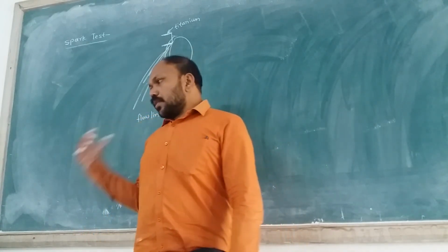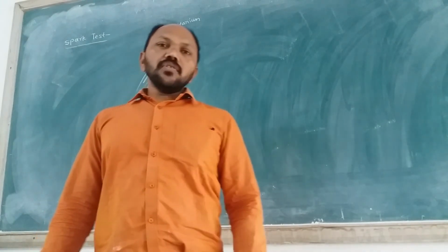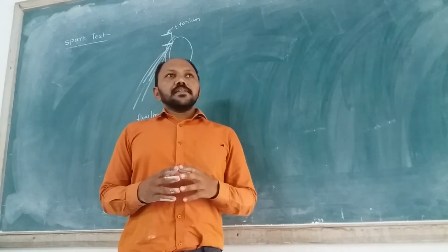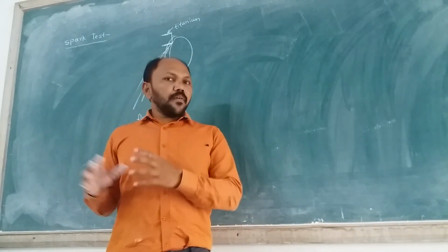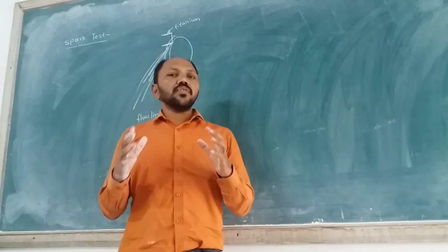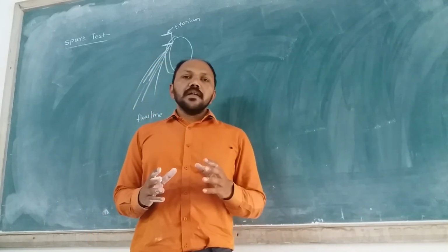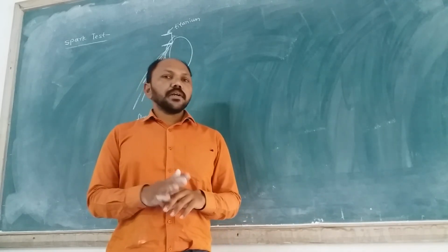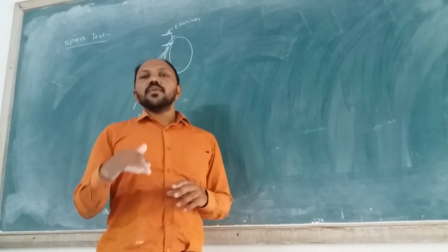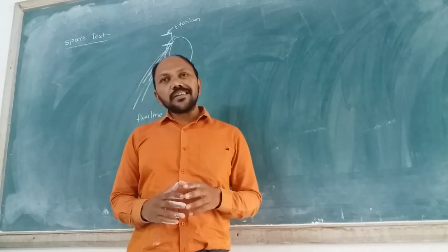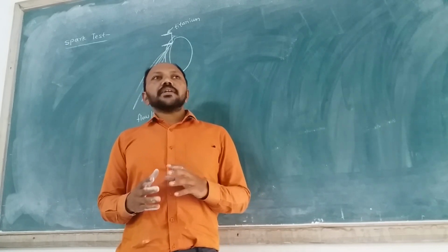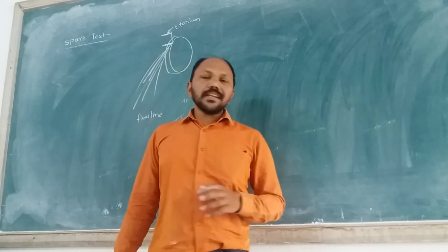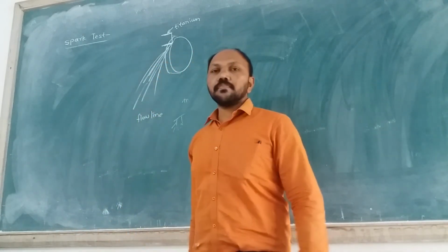So today we discussed three different topics. That is, if we consider the ferrous type of materials, how the sparks look in case of ferrous materials. And if we compare with non-ferrous materials, then non-ferrous materials do not show you sparks. And if we consider the metals or materials which are made with a forging operation, then that gives us some flow line like structure in that spark test.